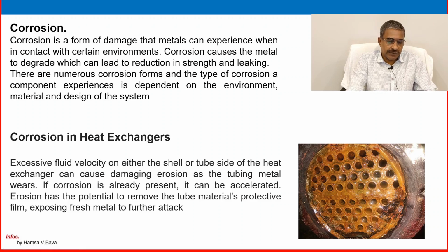So, coming to our point, corrosion in heat exchangers. Excessive fluid velocity on either the shell side or tube side of the heat exchanger can cause damaging erosion as the tubing metal wears. If corrosion is already present, it can be accelerated. Erosion has the potential to remove the tube material's protective film, exposing fresh metal to further attack.